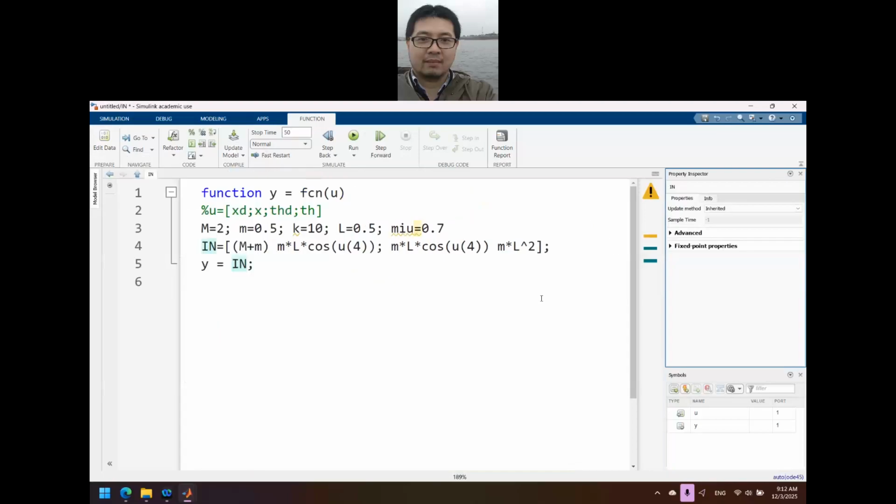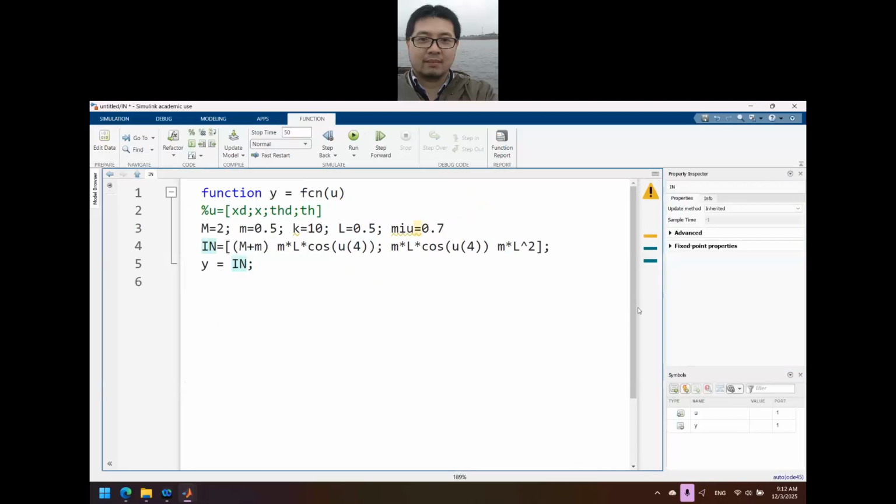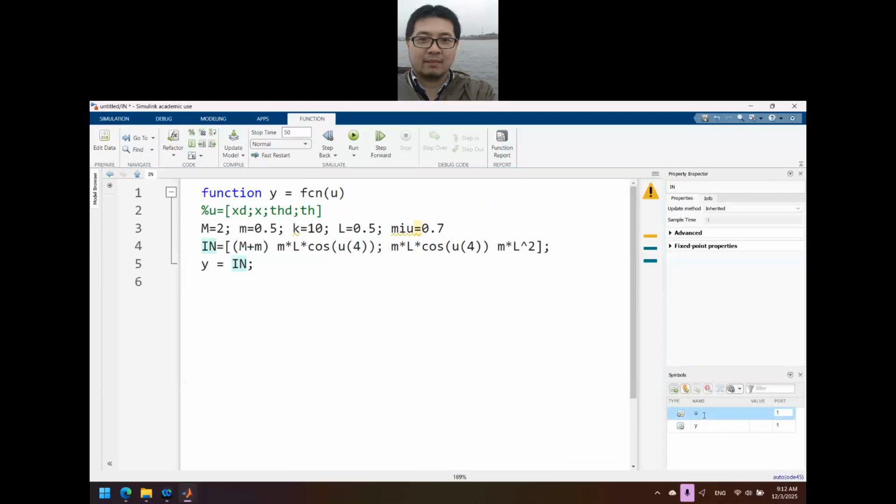Okay, and then you can see that here we are going to click U, which is the input. Click at the U over here, it gives us the input, and you can see that here we have the port 1 scope, which is the input, and then the size. For the size, you can see that by default it is -1. -1 means that there is no setting, and therefore we need to put in the size.